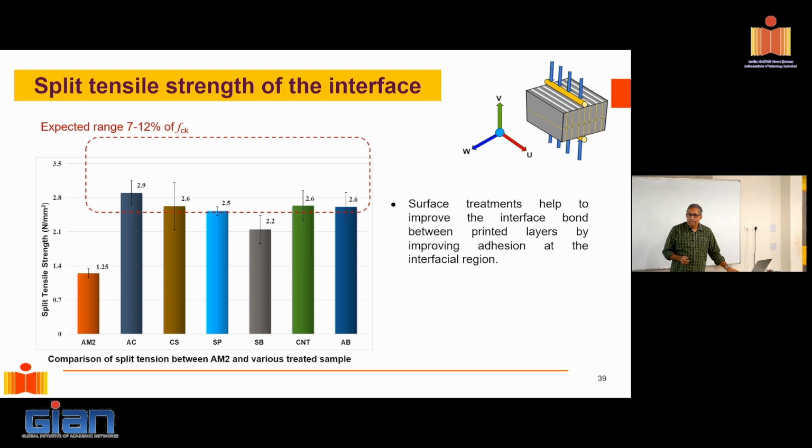Now, in the conventional concrete cold joint, we specify that the surface should be intentionally roughened so that there is proper adhesion. Is there some possibility like that? That's also being explored. We're trying to roughen the surface up as we're depositing it, so that the mechanical aspect of the bond is also improved. In fact, we had done some part of this here, where we did roughen it. Despite that, it didn't tremendously improve the tensile strength. There are no pores in place. There are very few, right?